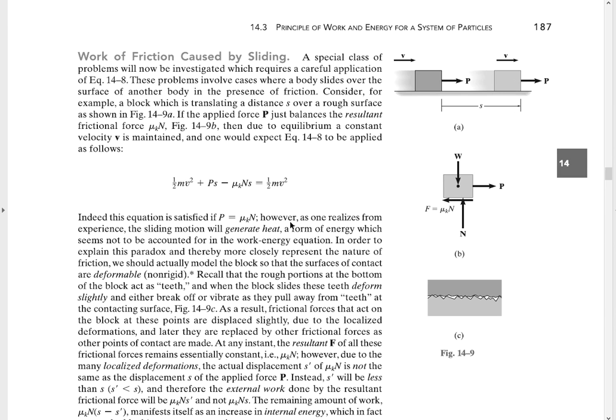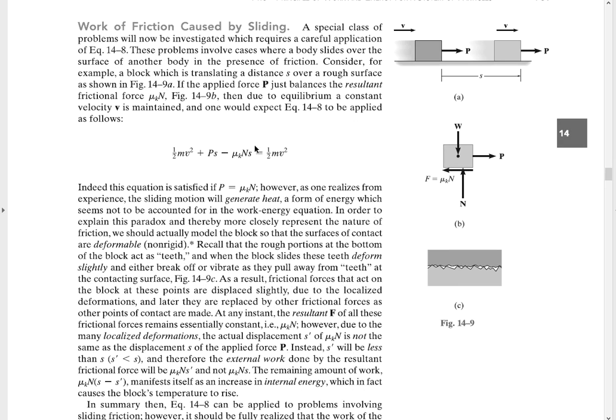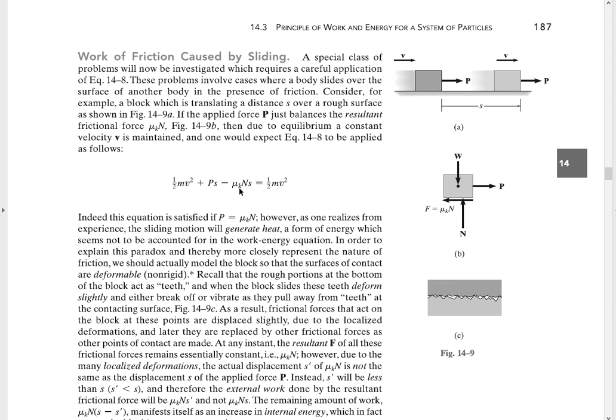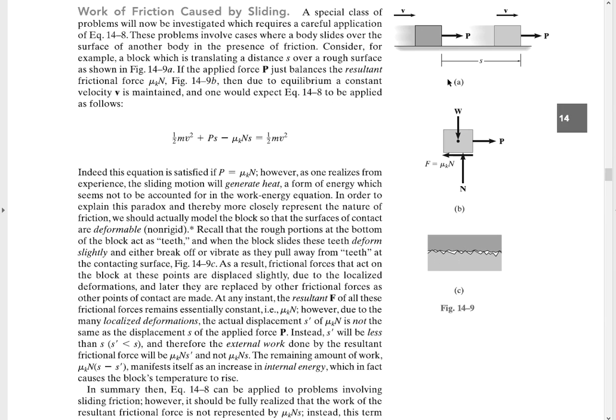The work of the friction force is always going to be negative and always opposing motion. It's the result of having friction force present and displacement happening. There is relative motion between the two surfaces. This generates heat, but you also have a change in the structure of the surfaces. Say this is an abrasive block and this is a piece of wood. As you slide it, you're going to produce sand dust and scratches, and that's a change in the structure of the surface.